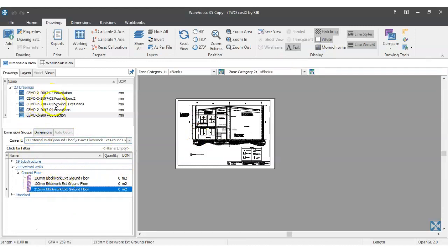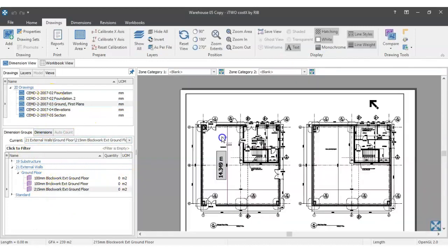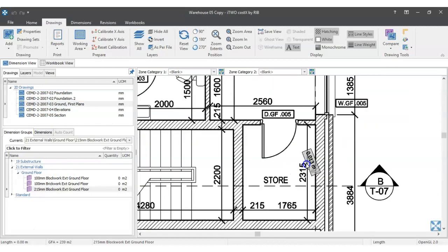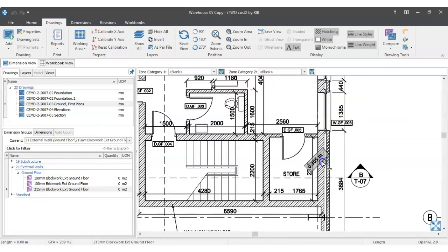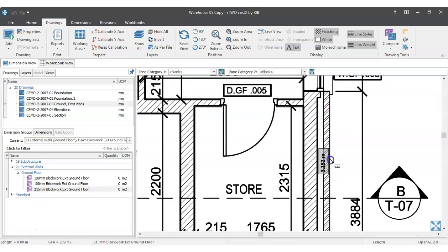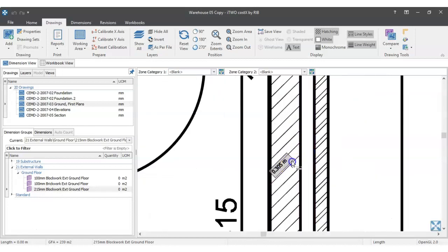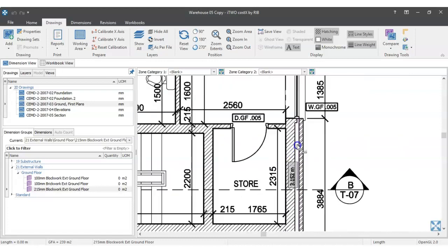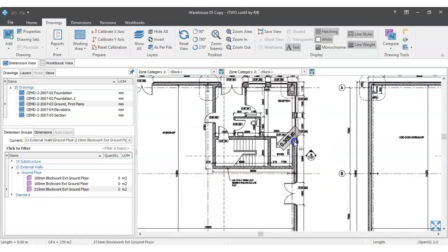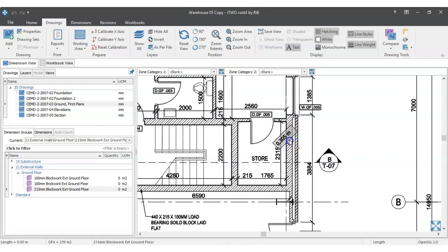Now remember, I think some of you were getting confused with the little project I'd given you at Christmas. Your external wall construction does include everything from the outer leaf through to the inner leaf. So even though that's an inner leaf, it's still an external wall. It's still part of the makeup of the external walls. And we're measuring all these items separately.